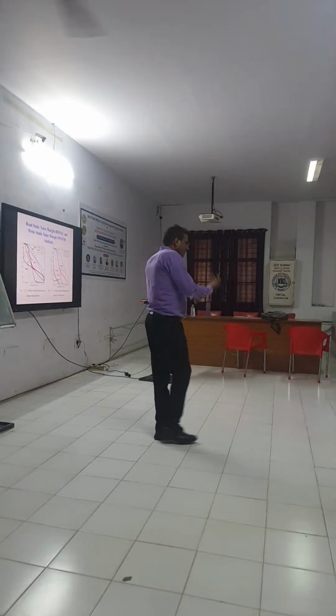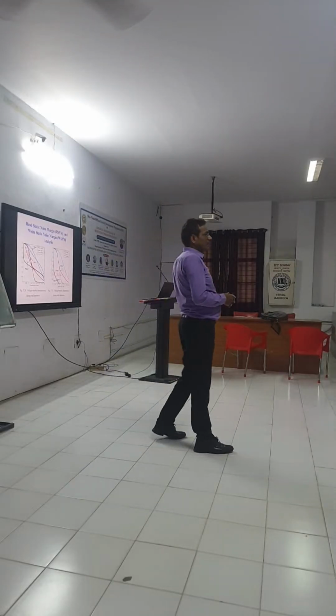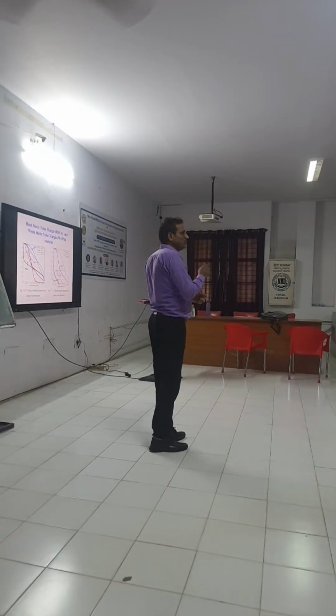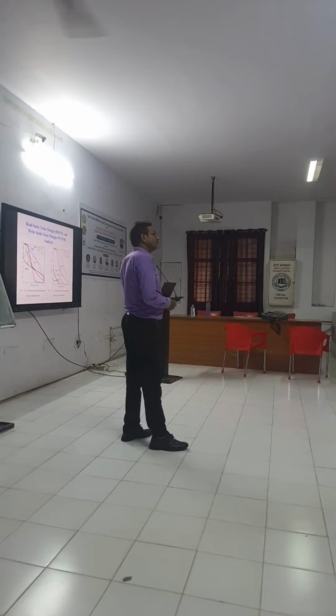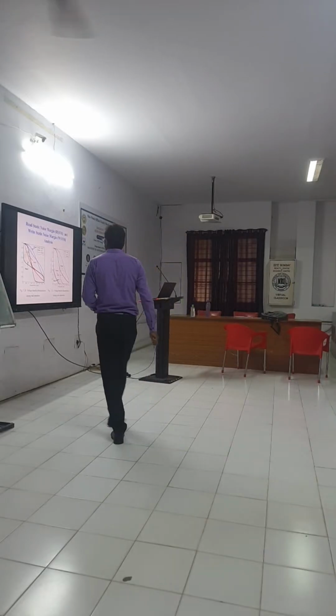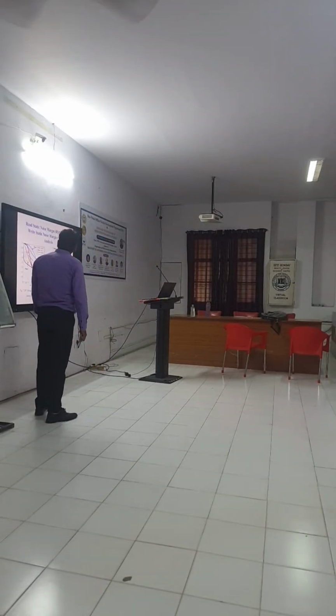During hold, we are not reading or writing. That time also noise is coming and being tolerated by your circuit. So we are checking the maximum noise. If the maximum noise tolerating capacity is higher, it means more stable, more good. Stability is very good. So see, static read noise margin and write static noise margin.